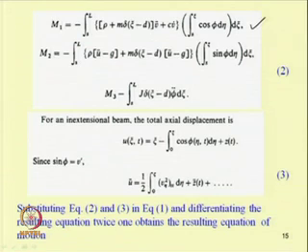So, our m1 equals minus integral from S to L of rho V double dot. We have added the damping also, and we have used this Dirac delta function to write the position of the tip mass at a distance d from the base. Rho is the mass per unit length of the system. So, we can write the equation of motion, or we can write this m1 due to lateral moment, into integral S to zeta cos phi d zeta.